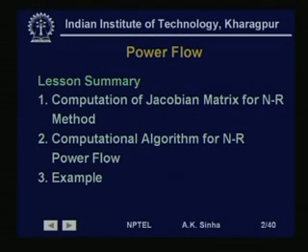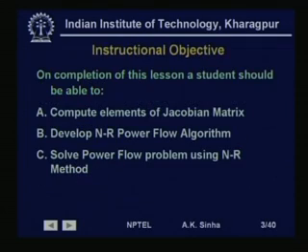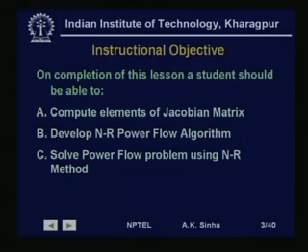Then we will talk about the computational algorithm for Newton-Raphson power flow, and we will work out one example for a small power system, showing how we do a Newton-Raphson load flow or power flow. Once you complete this lesson, you will be able to compute the elements of the Jacobian matrix. You will be able to develop the Newton-Raphson power flow algorithm and solve power flow problems using the Newton-Raphson method.